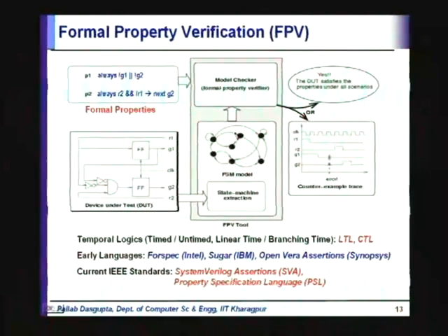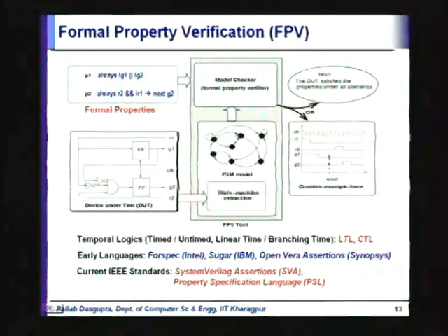In other words, it has to explicitly traverse this state machine to guarantee that the property holds, right. And for a typical design, this state machine is going to have billions of states. So the whole challenge is, how do we check those properties on these billions of states without getting into too much complexity, right.